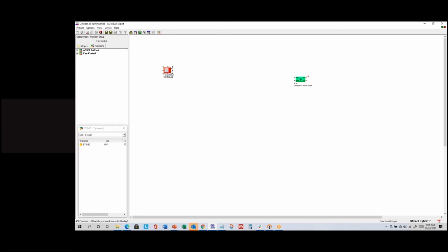And then to remove an icon from the group, you could just do a right-click delete. Be careful, though, because clear and delete are different. Clear resets all the settings for that icon back to 0, but doesn't remove it from the group. And delete kind of does the opposite. It removes it from the group, but doesn't change any of the settings. So delete's all I really need here.